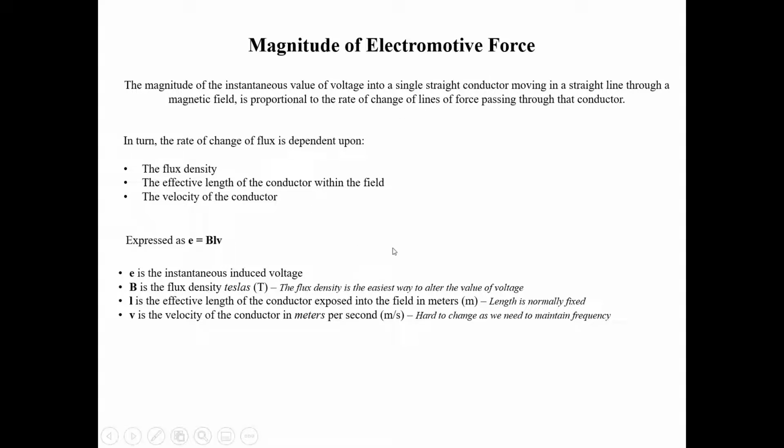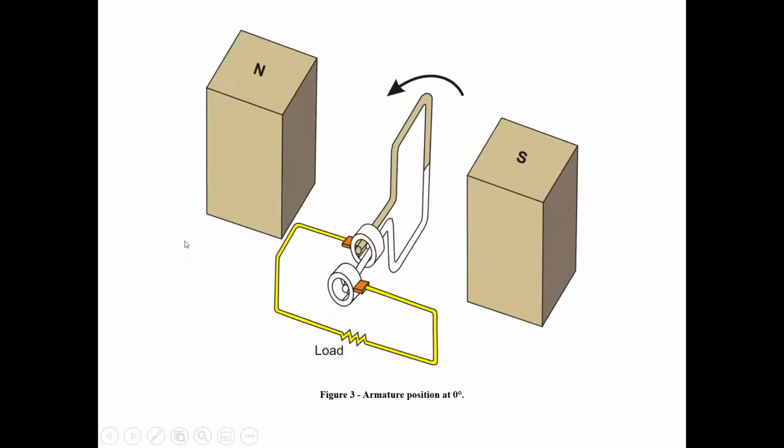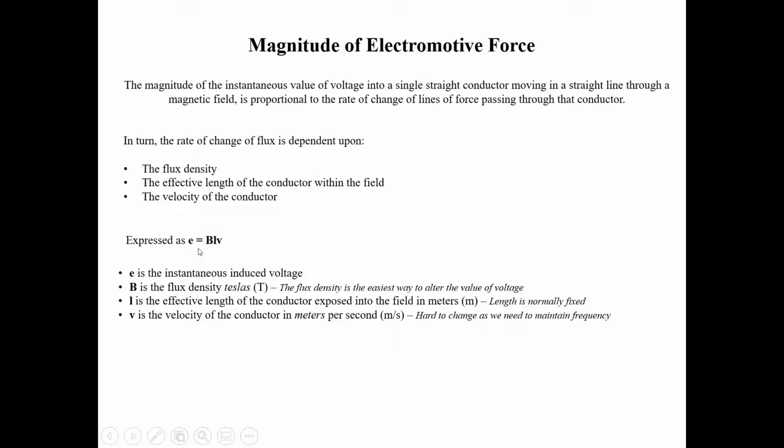Okay, because if we have a prime mover like on a generator, we have a combustion engine that's spinning the armature windings within the field windings, and that's going to generate a voltage depending on how fast we're spinning it. Faster motion, higher voltage. More flux density, higher voltage. This formula right here is going to show us that these are all directly proportional. So the amount of EMF is going to increase if this increases, E goes up. If the length increases, E goes up. If the velocity increases. So if any of these values increase, we're going to get a higher output voltage.